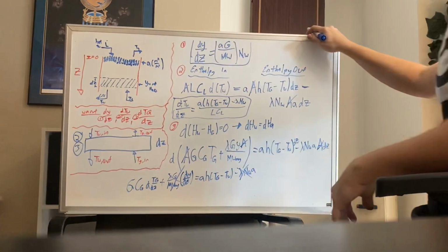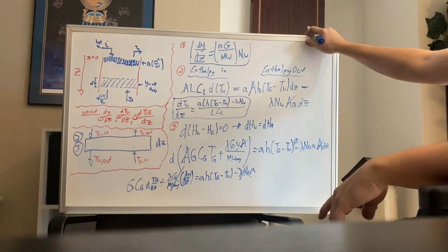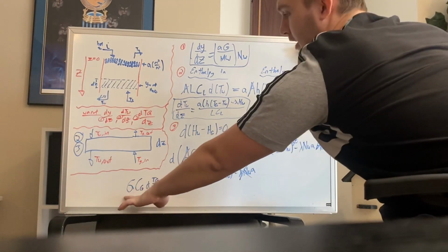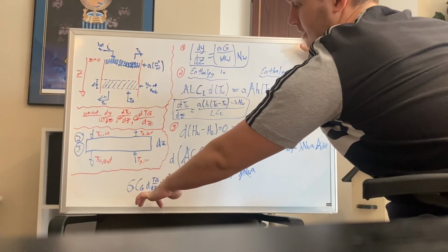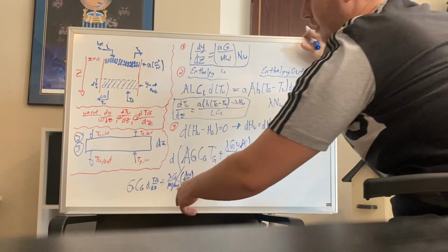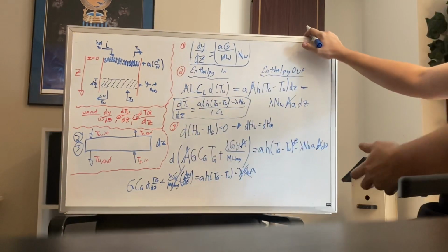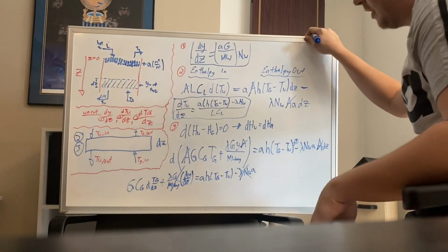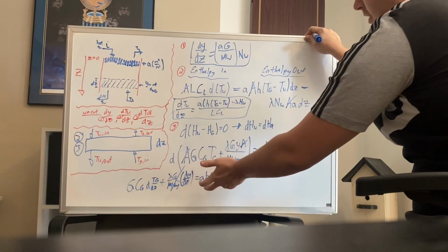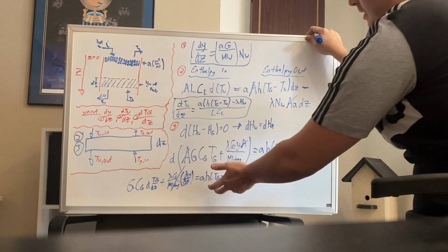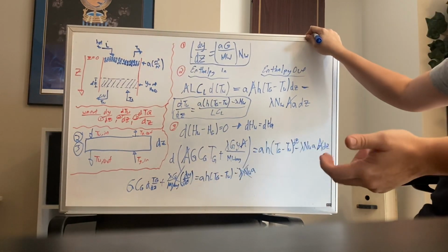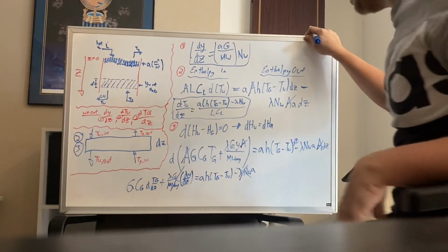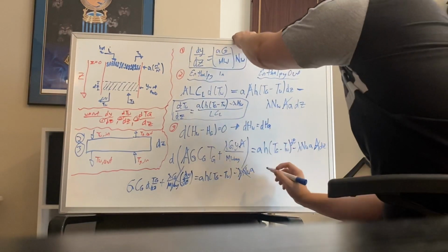And so we're actually left with this very pretty result: this gas flow rate constant multiplied by this heat capacity of gas multiplied by the rate of change of the temperature of gas over the rate of change of traveling through the cooling tower. And this is going to be equivalent to the specific area multiplied by the heat transfer constant multiplied by the difference in the temperature of the gas and the water.